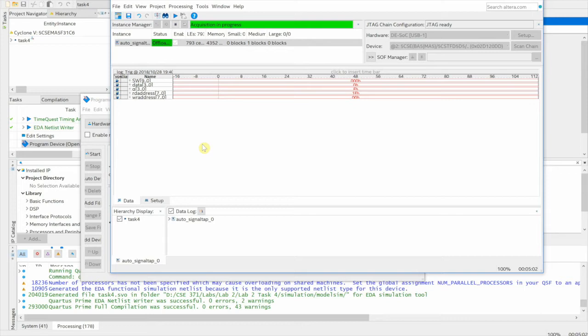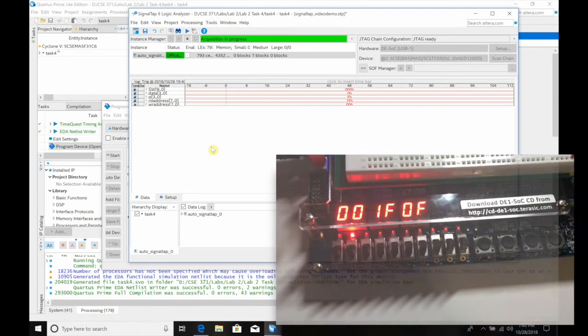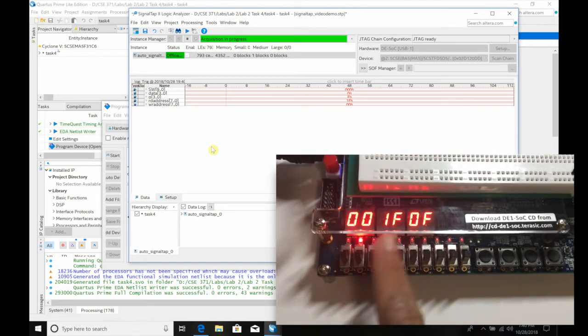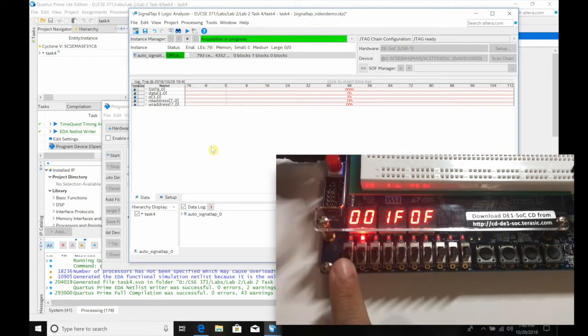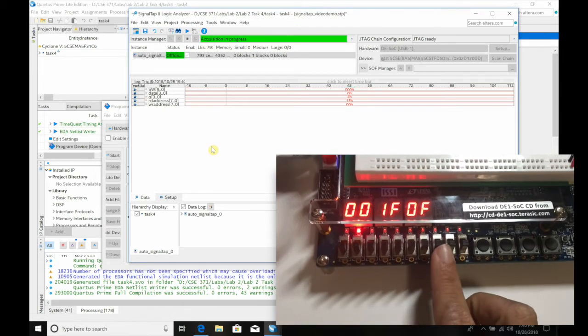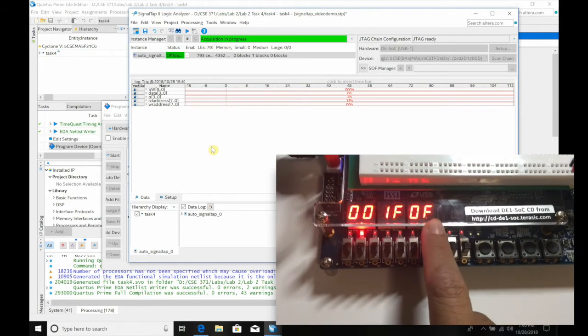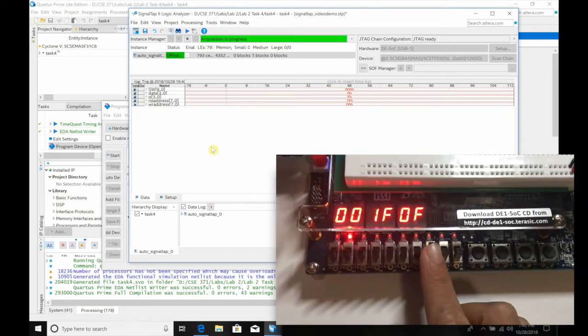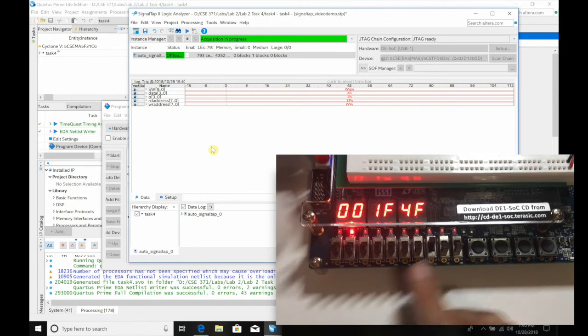And in the case that we want to read it, we can read from that memory what's in that read address. On my board, I'm going to write something to this address, 1F. And I'm going to replace the current value, which is F, inside of the RAM with a 4.